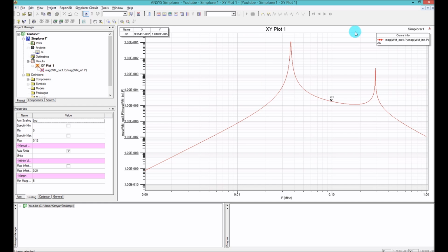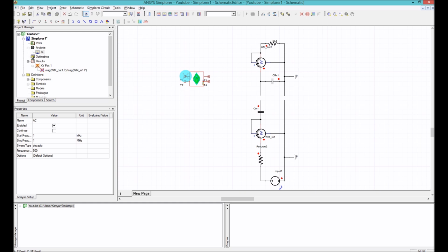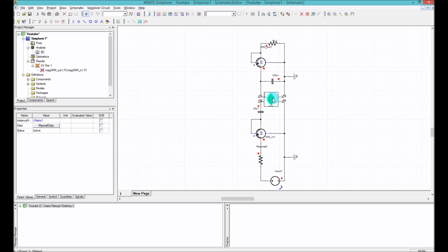Okay, now when you do it on the logarithmic view, you can see here that you have two resonant frequencies. That means that your CR and CT are not in the right place, or the terminals, which is what it was telling you at the beginning, through terminology. So it happened once to me, so hopefully it never happens again.